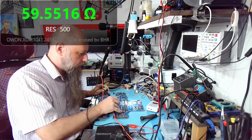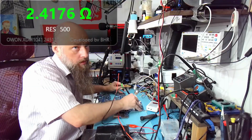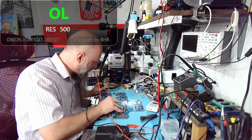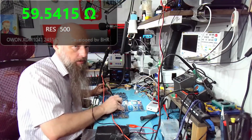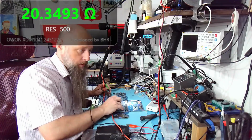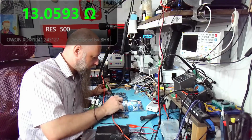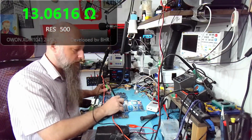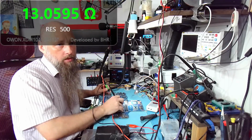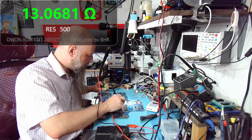Okay, we have 59 ohms on this coil, so this must be memory. And on this one we have 2.3. So is it just a different CPU, or is it shorted? 60 ohms versus 2 ohms. That doesn't sound right. Now on this one, this is the one that had, oh yeah, there you go. Since one board is laying on top of the other board, that's why I was making a short somewhere. So we have 13 ohms on the rail that the original board had a shorted VRM.